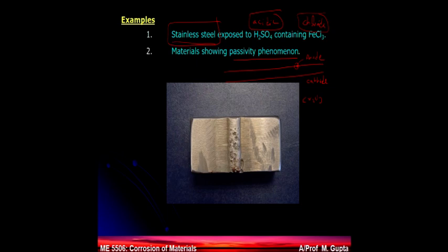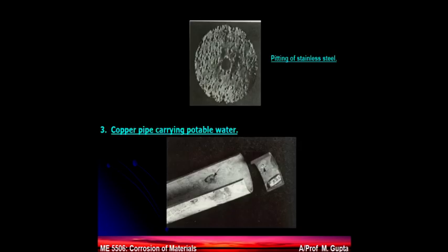Now the pits appear with some kind of a circular appearance. It shows another piece here where the piece is welded and you see these black holes here. These are all pits. So you can see them with your eyes, but the question is where to see them. That is the problem. Here is another part of stainless steel with a lot of pitting in there. After removal you see the black holes are there. They need not be exactly circular, but somewhere elliptical also.